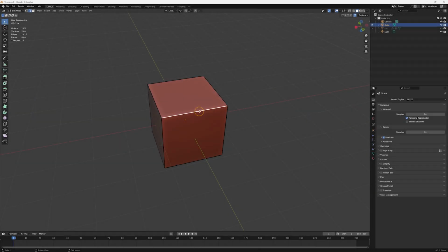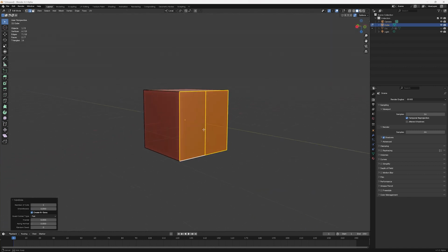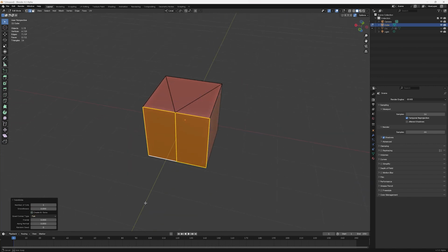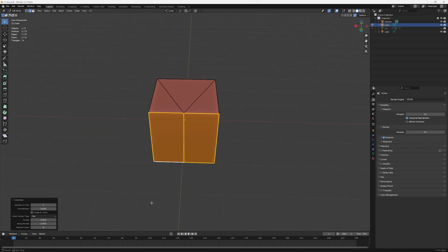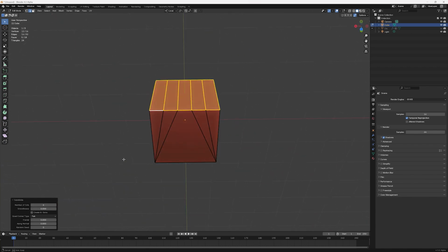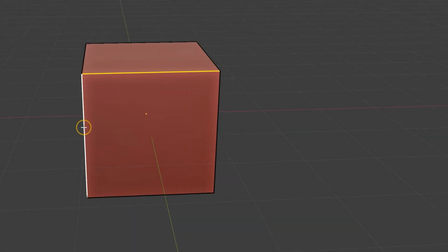If we select 2 opposite edges to subdivide, we split the face they share into 2 or more quad faces, while the original adjacent faces become n-gons, or a collection of tris and quads. The next possibility for an initial selection is 2 adjacent edges.